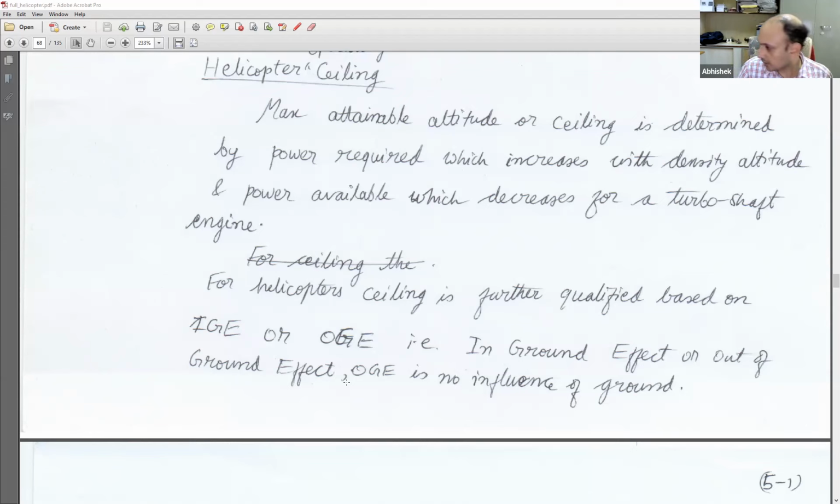So for dynamic stall, say I have an airfoil, any kind of thing. We'll assume this is an airfoil. My phone is an airfoil. Dynamic stall happens only in scenarios where your airfoil or wing is doing repeated motion, and that's what happens for helicopters.